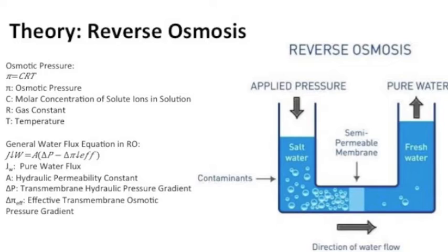In the reverse osmosis system, an external energy source pressurizes the saltwater solution in the bulk feed, overcoming the osmotic pressure of the system and forcing water through the semi-permeable membrane while retaining salt. The desalinated water passes on as the permeate, and the remaining concentrated salt-water solution leaves the cell as the retentate. The water flux quantifies the amount of water that traverses the membrane as seen from the following equation.